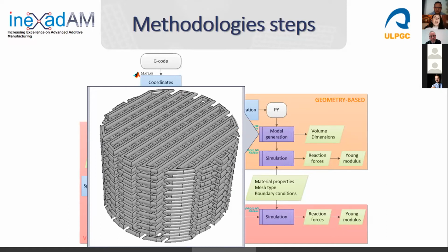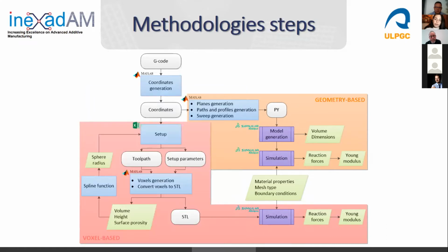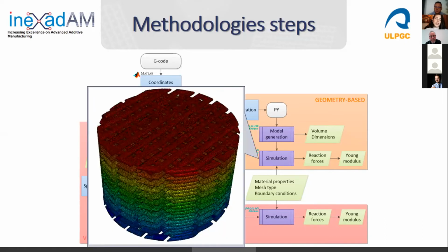In this case, we have a displacement on the top face, and after that, we obtain the results of the simulation, obtaining the reaction forces in the base face, and calculating the Young's modulus of the part. So we know the stiffness of our model.